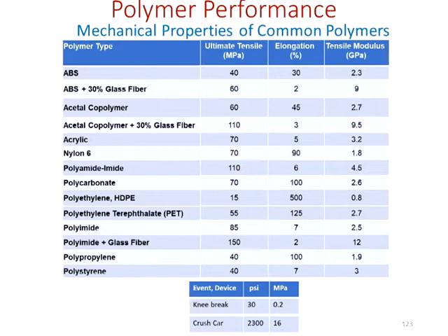110. Likewise, the ABS polymer, which is used in Legos, when it's glass fiber reinforced, the tensile goes up. So that is one of the take-home principles that we learn about tensile and elongation and modulus, that it can be modified depending on what type of additives we put in. And one take-home point from this is that when we add glass fibers, the tensile is increased. Okay, so we increase tensile by adding the glass fibers.